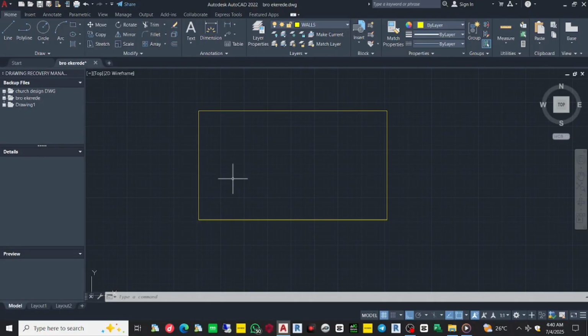So now let's take for instance, if you want to continue on your former procedure, you press enter on your keyboard. You simply told your AutoCAD that you want to repeat the same procedure you've done before. That's you want to still draw line. So you see, I've drawn the line. There's escape. So let's assume this is a mistake. I want to cancel it. How do I do it? First, one way I can do is by highlighting like this and click delete, or I can simply press Ctrl Z on my keyboard. You see, when I press Ctrl Z, it disappeared. I'm telling my interface that I no longer want to do it. That is how to undo.